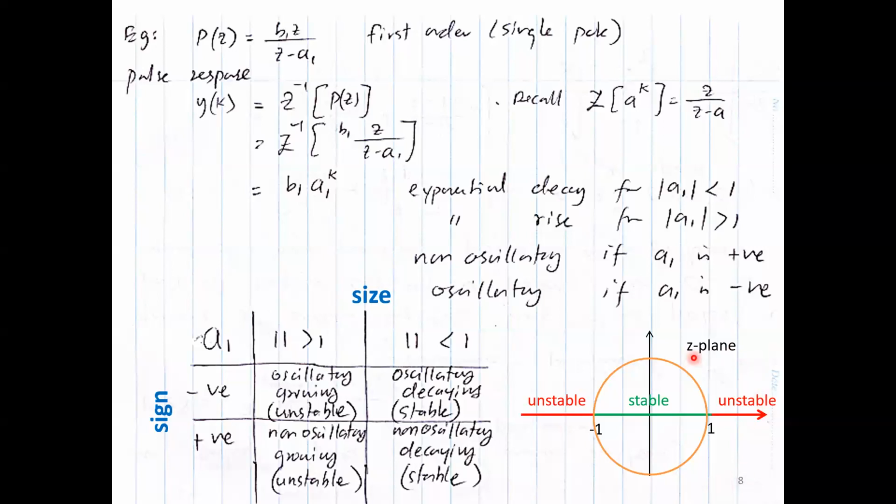Now it is the Z plane, and for stable cases the poles are within the unit circle. And if the poles are outside the unit circle, the plant is unstable. So this is a mapping from continuous time to discrete time. The entire negative half of the S plane is mapped onto the unit circle in the Z plane. Okay. So that's what essentially is happening here.